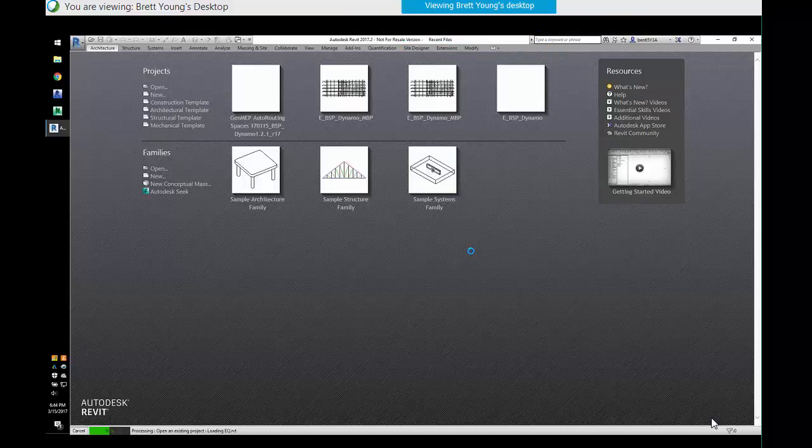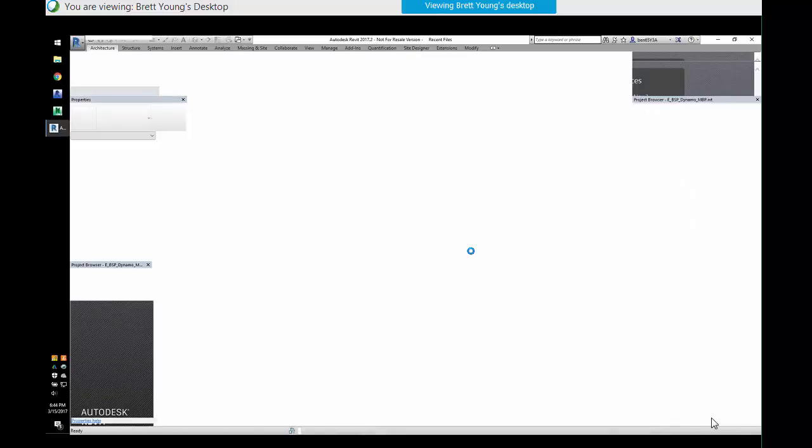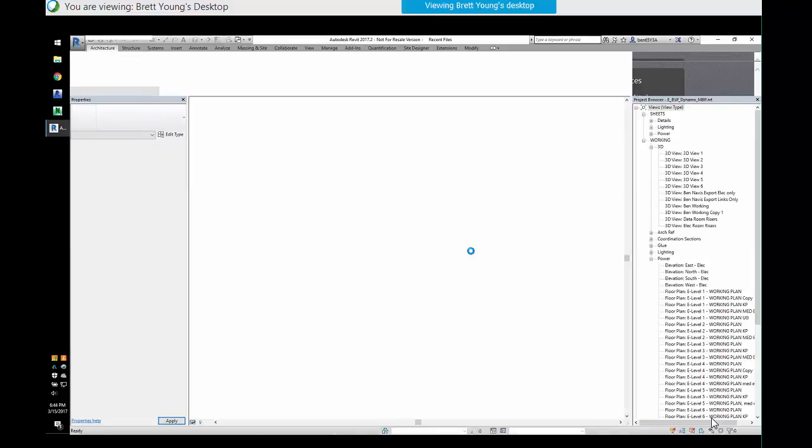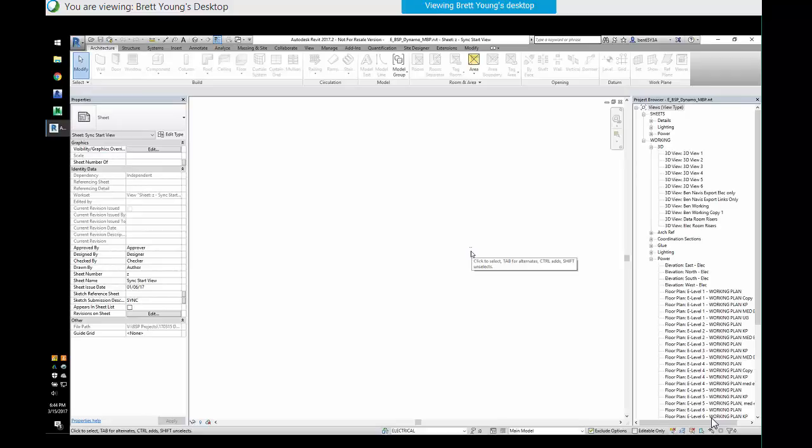So in this example, we have an electrical model with an M and a P and a medical equipment link in Revit, right? And one of the things that I found in Dynamo that isn't perfect is that I would like to reference equipment through Dynamo from links. And so I found that you have to do some tricky things. I'm using, I think, Spring nodes to get elements that way, but I really don't like using any modules that I can't use on a new computer fresh, right? I don't want to have to check dependencies, right?